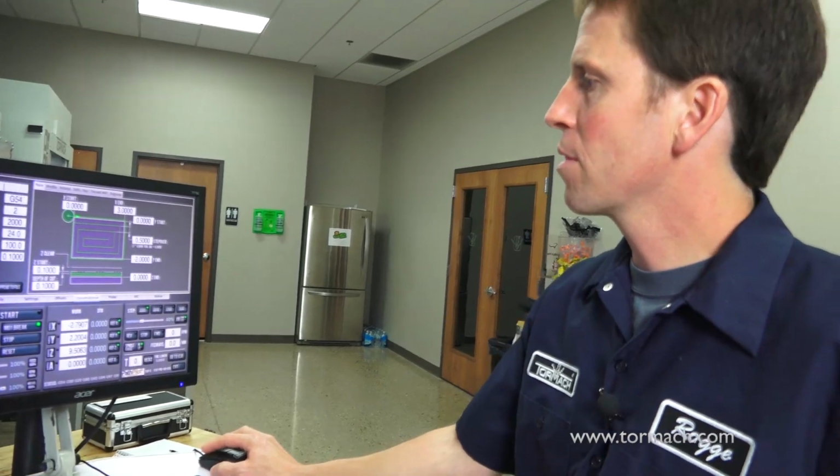So that's an overview of the conversational tabs in PathPilot and the milling interface. The idea here is, you're not going to be able to handle everything that you'll want to machine with this, but the simpler tasks, like facing off a part or squaring up some stock, should be much faster to do in conversational than in CAD/CAM. And there are a couple things like thread milling and engraving that can be really clunky in CAD/CAM. That's very nice to be able to do right here at the interface.